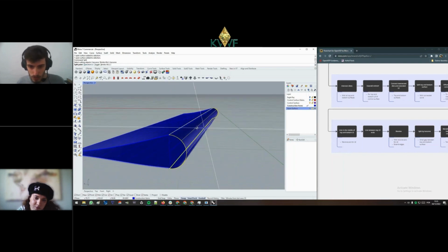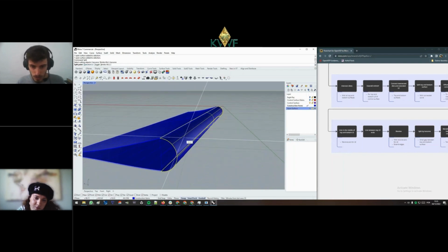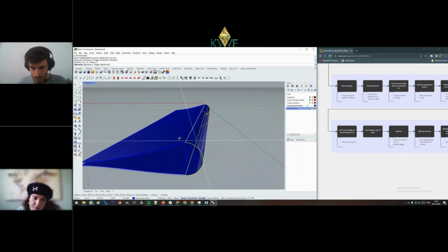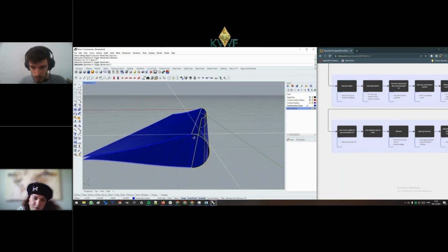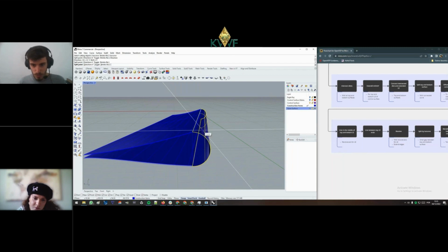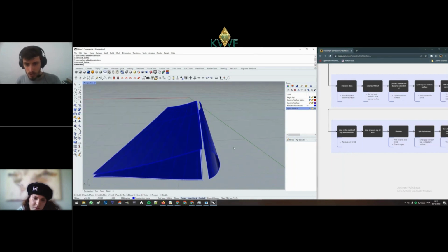And this we have to split with the V direction because the U direction is on the leading edge side. So with the V direction, we have a span-wise cut here. So I can cut it some distance apart from the intersection here, and same thing for the bottom. And then I will delete these two surfaces.